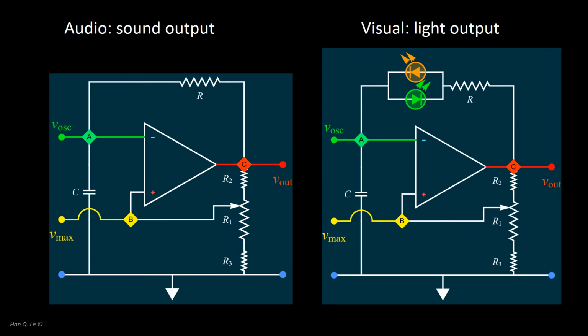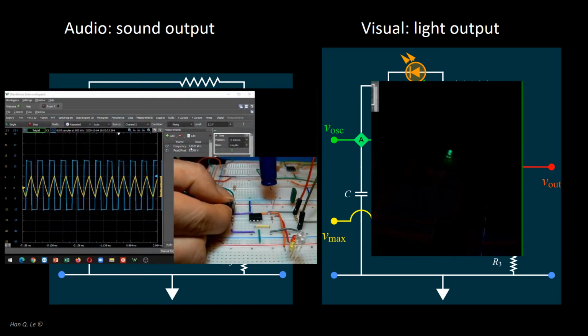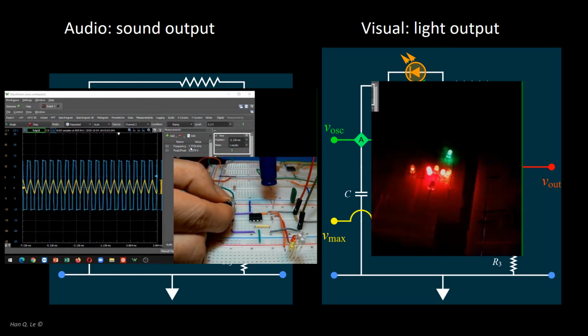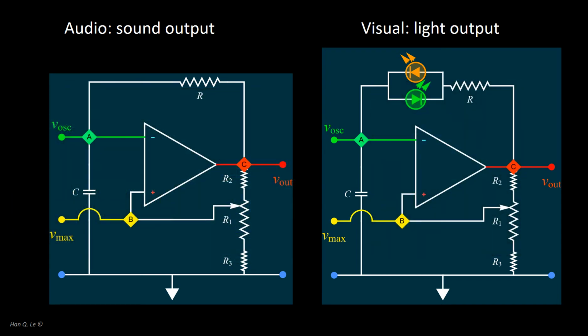This circuit offers a study of two topics: the resistor-capacitor timing effect on frequency, and also a demonstration of the op-amp property of high open-loop gain that leads to saturation and instability. It intends to give the student a direct sensory experience, that is, audio and visual, to reinforce the learning about RC time control and frequency.